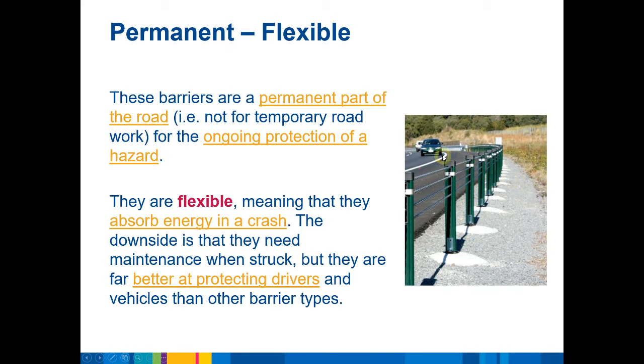If you have a very low car, like a Ferrari or a Lamborghini, that would go straight under the barrier. Because again, the barriers are designed with a certain amount of tension. They're designed for the 85th percentile vehicle height. It might be 95th percentile, I can't quite remember, but it certainly doesn't cater for everything. However, if you can contain 95% of the vehicles that are on the road and help keep them on the road, that's a really good outcome.